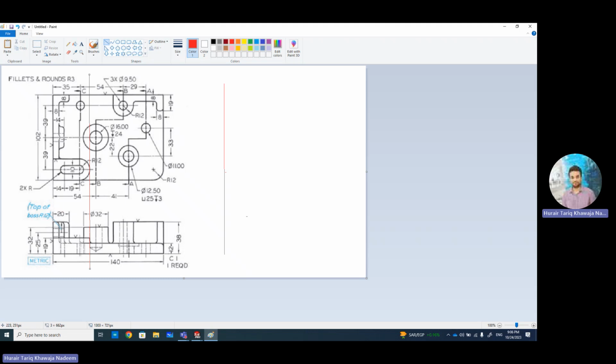And we'll make the circle at the end because the circle, we have to select this face and then extrude 14 millimeter from the back side. Okay, so let's make this profile. Okay, so this is eight, this is eight, this is eight, and 39 from here, 39 from the center. And what else? Okay, so eight, eight.